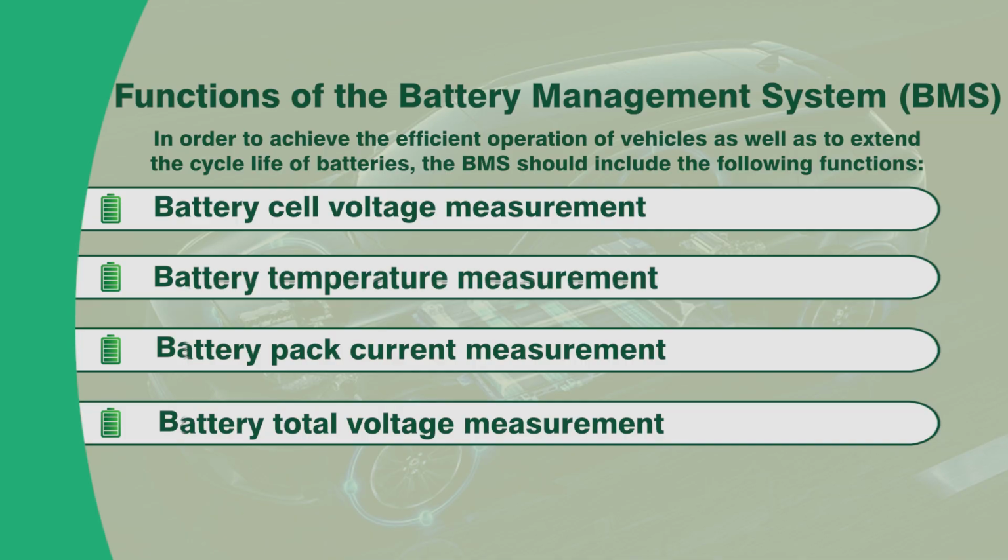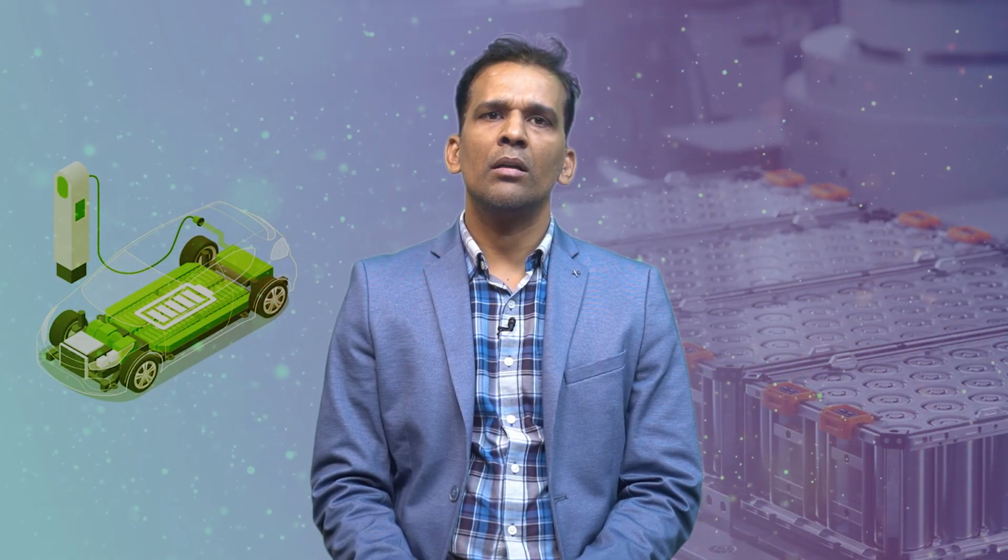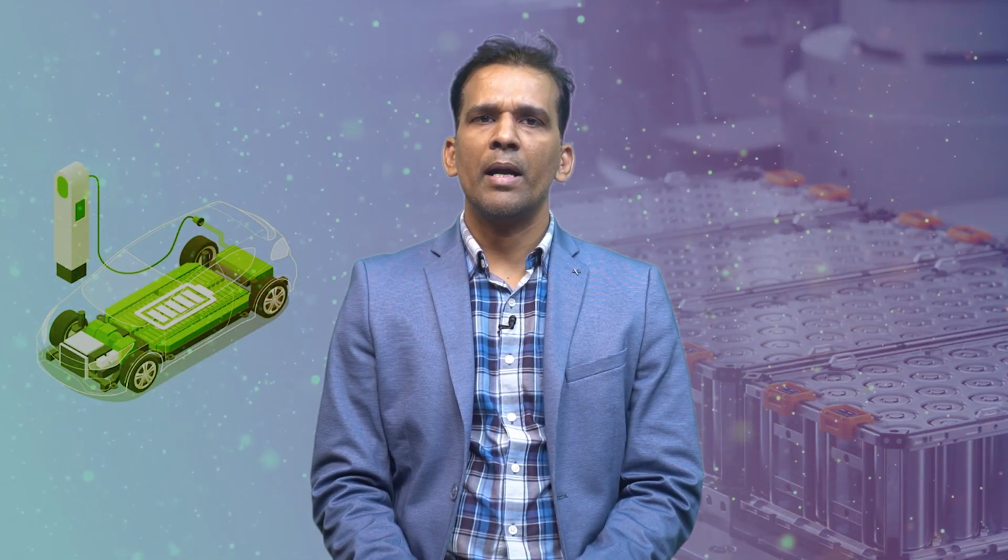The next one is the battery total voltage measurement. It is very important to monitor the ultimate battery pack voltage, because if we consider the load, the load is very much concerned about the total battery pack voltage level. That is why we are measuring the total voltage of the battery pack.